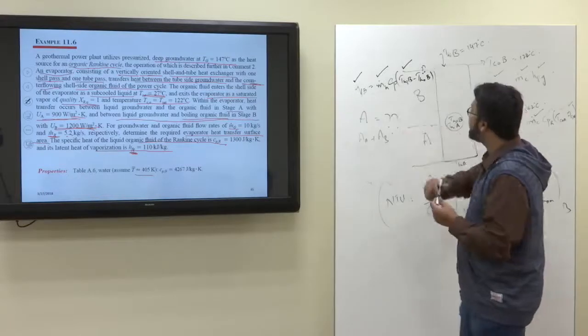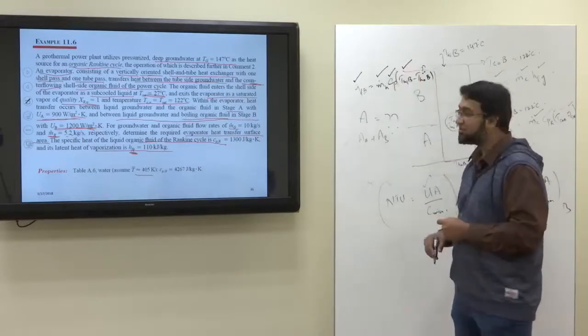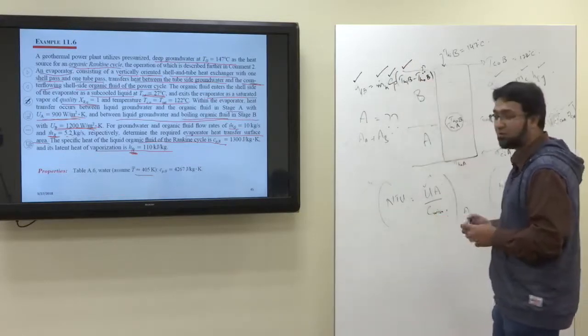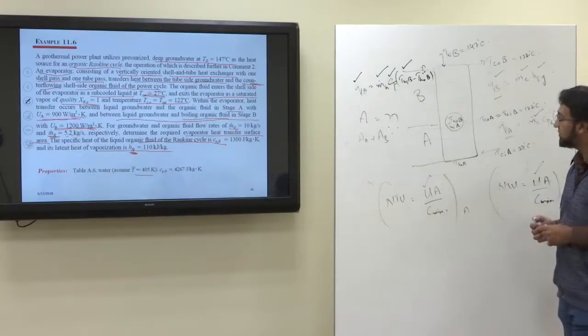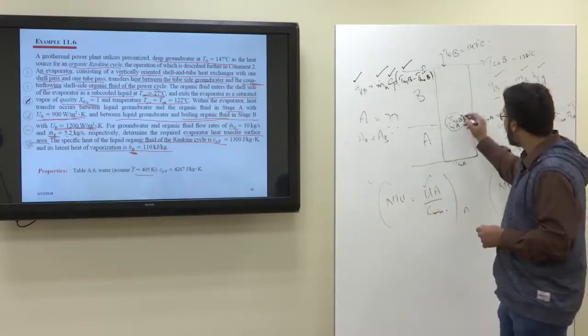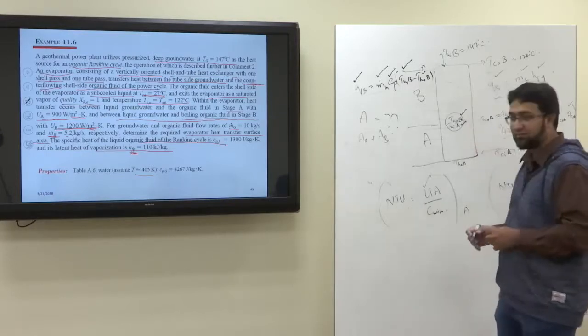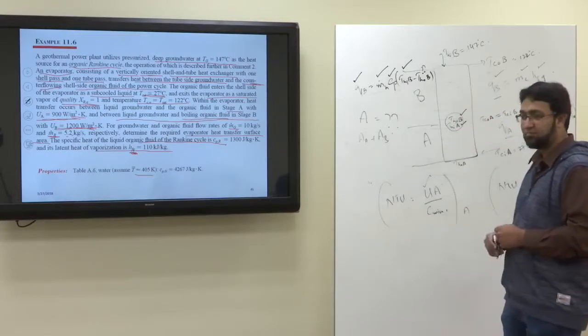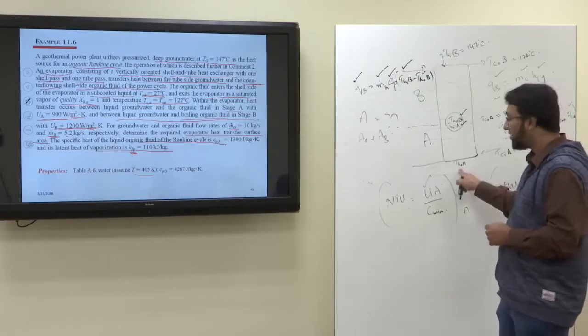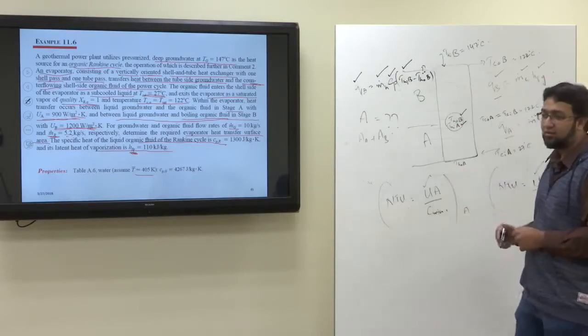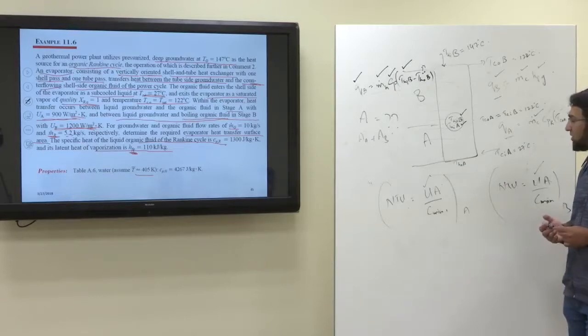So now you know Cp. Based on that Cp, you will find out what is T hot outlet B. Okay. So now we know THOB, THIA, because these two are the same. Okay, we need to find T hot outlet A. Can somebody tell me how we can find that?